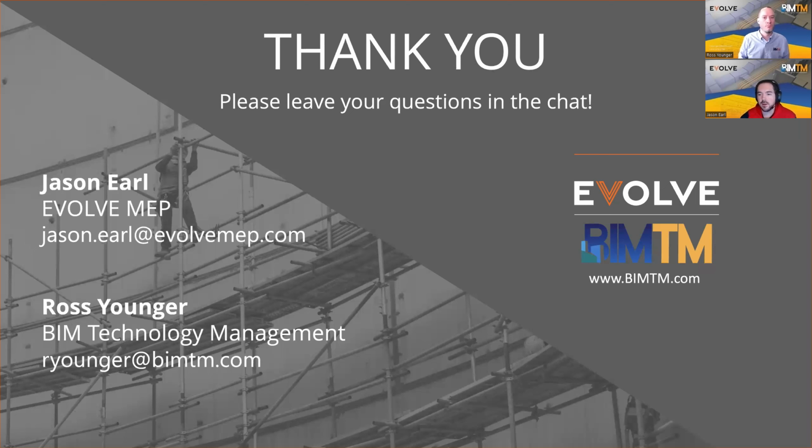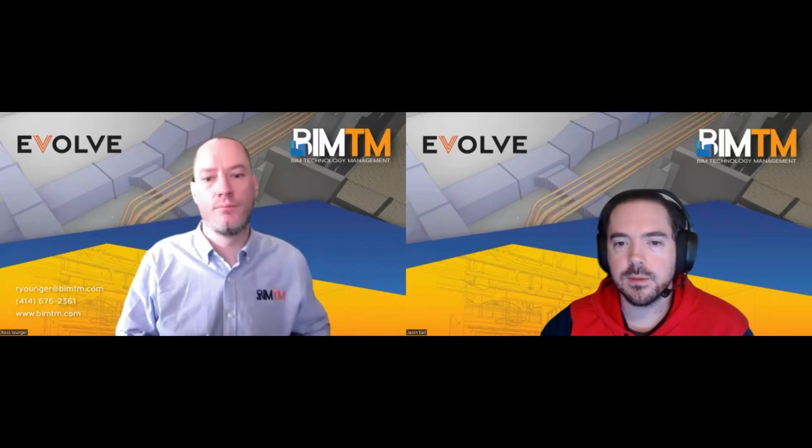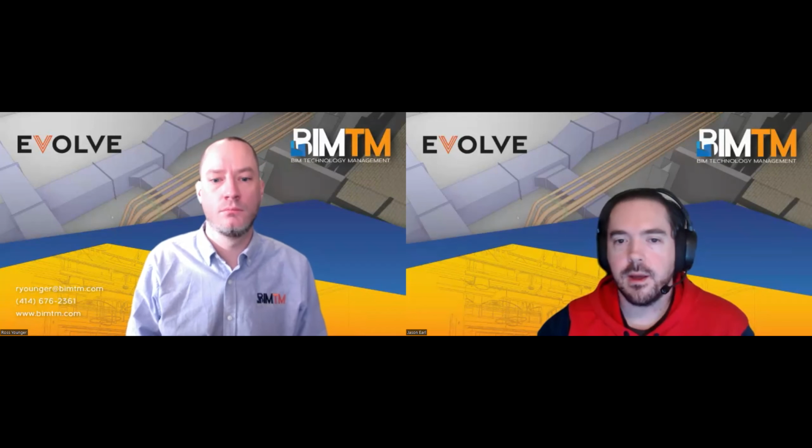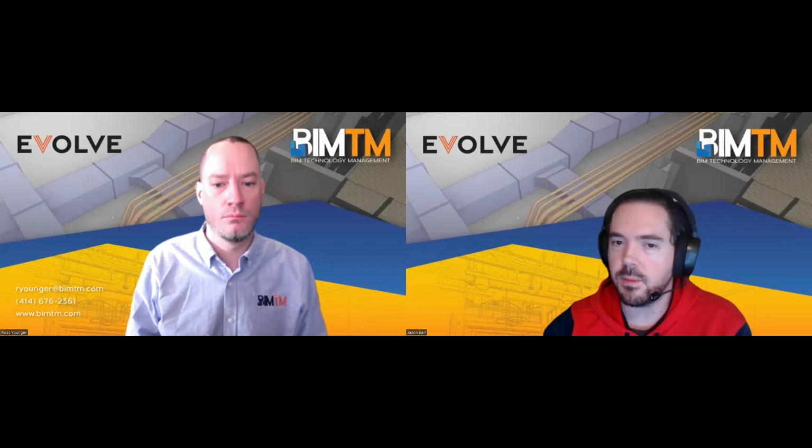a single object. The other option takes a little more time, but especially if you're going to use a point cloud of an existing structure, go ahead and model some of those elements from the point cloud. Model the floors, the roofs, the columns, the walls. That will help you a ton, having the actual 3D elements in your model, so you're not relying on those points. Because as you start to zoom in, your point cloud starts to become more of a point mesh.